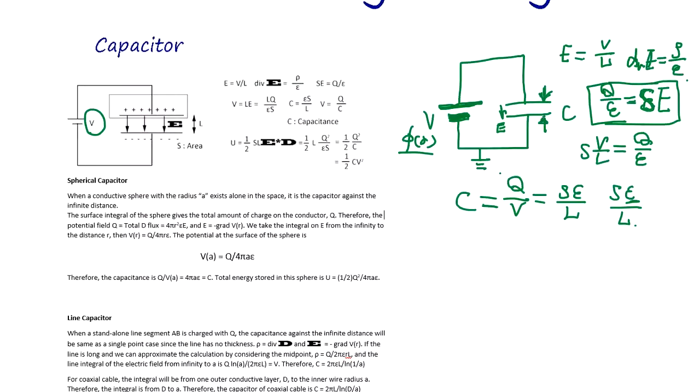So what they do to make a capacitor is use plastic sheets with metal on both sides. The sheet width is as thin as possible. But when you make it thin, there is a breakdown voltage. When you apply voltage, if it's too thin, it breaks down and the electricity goes through.